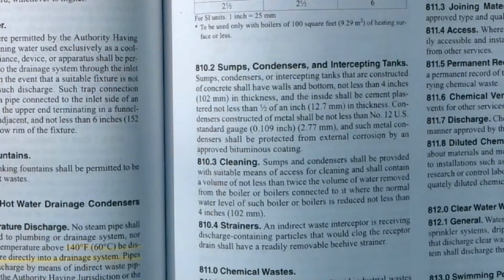This section 810.2 tells you about the tanks, the condensers, and the sumps. They're all constructed of concrete, and they shall have walls and bottoms not less than 4 inches in thickness, and the inside shall be cement plastered, not less than half inch thick. The condensers constructed of metal shall be not less than number 12 U.S. standard gauge, and such metal condensers shall be protected from external corrosion by an approved bituminous coating. So what they're doing is they're telling you, you either go concrete, which is 4 inches thick, or you go